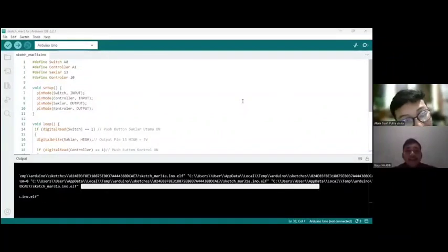Here is the code for the DC motor circuit. First, define switch 1 on pin 0 on the Arduino Uno, switch 2 on pin 1, the Cycler output on pin 12 on the Arduino Uno, and the controller output on pin 3 on the Arduino.